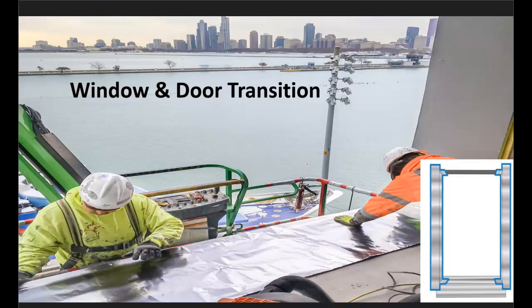As a window and door transition, you can now wrap your openings with it. If you're going to fit a curtain wall on top of it, typically they're using those silicone sheets around it to tie in to your wall. Well, you have to use silicone a lot of times. Silicone doesn't stick to much but more silicone. So if this were a polyethylene facer, it wouldn't stick. But as a stainless steel, there's no issue with the silicone sealant adhering to it.